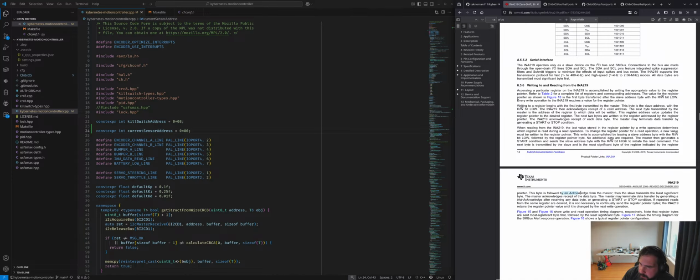The byte is followed by an acknowledgement from the master. The device transmits the least significant byte. The master acknowledges the data byte. The master may terminate data transfer by sending a not acknowledge after receiving any data byte, or by generating a start or stop condition. If repeated reads from the same register are desired, it is not necessary to continuously send the register pointer bytes. It retains the register pointer value until it is changed by the next write operation.